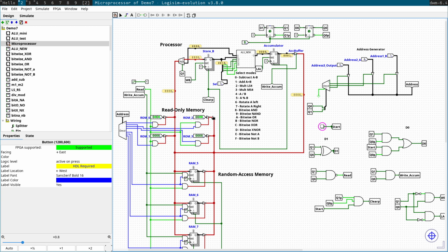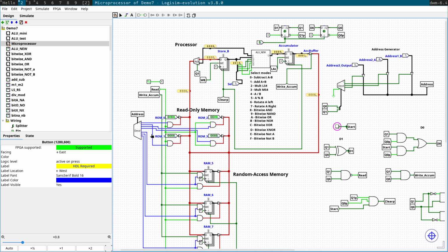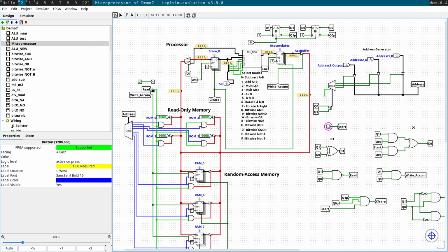So you want to start with a read-only memory, which you could type in manually. And then you want to select your addresses with this address generator, which all it does is, as the clock up here is counting up, it goes through each one of these addresses into the address decoder over here, which then, depending if we're in read or write mode, helps us select which of these units we're going to be talking about and whether we're reading from them or writing to them, obviously.